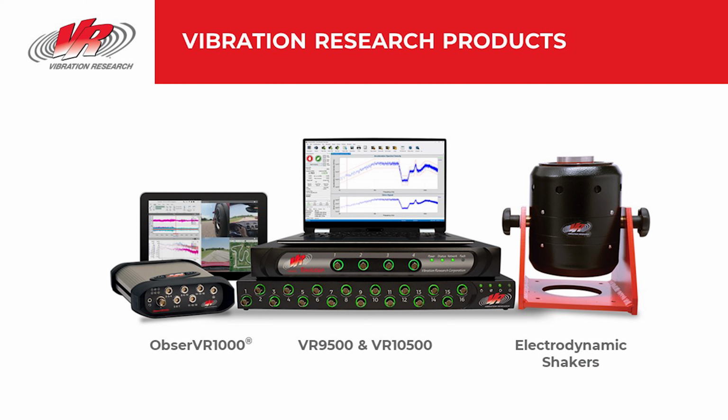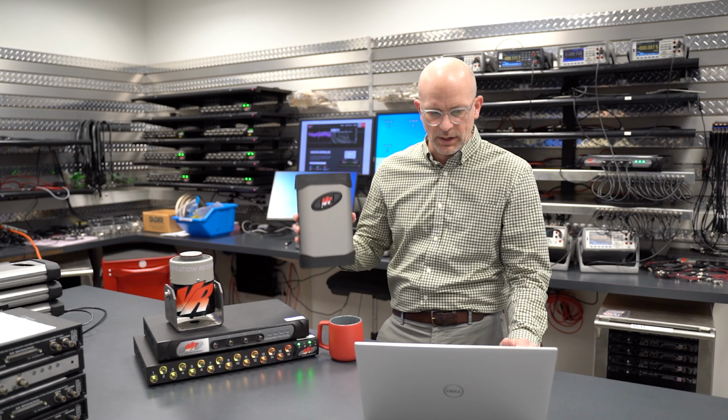It's scalable to 512 channels and features a control sample rate of 256 kilohertz and 4 outputs for multi-shaker testing. We also have a couple more outputs that we'll talk about when we get into the VR10500 in just a moment. The controllers themselves use a high-speed RISC processor that can process large data sets efficiently and run vibration tests at low and high sample rates. They are capable with all electrodynamic and servohydraulic shakers and it can function as a data acquisition device as well. It's just not as portable as the next piece of hardware, the Observer 1000.